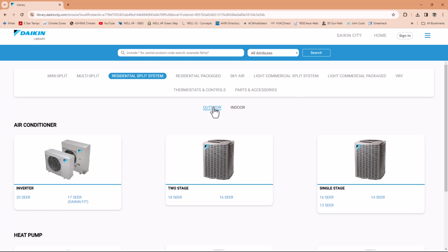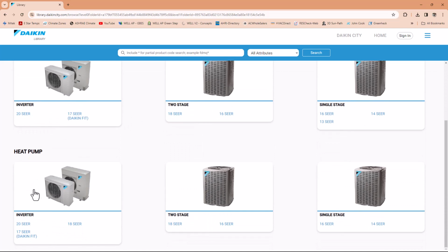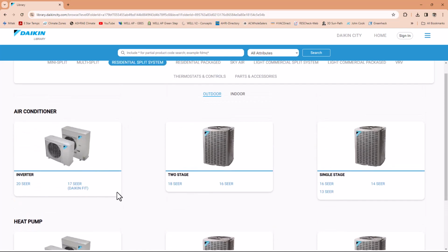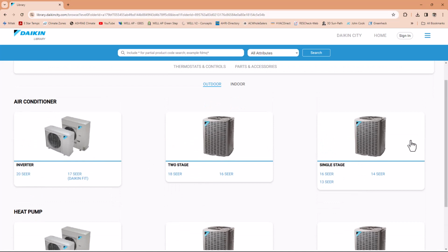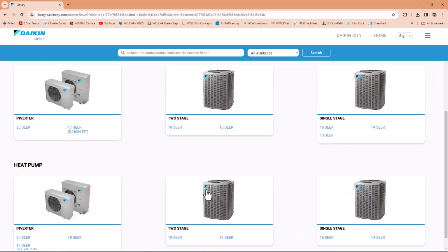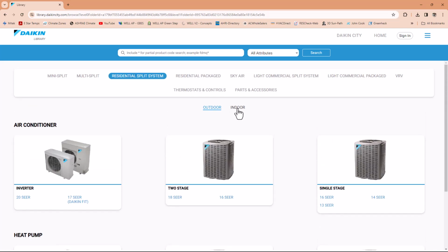And remember, this happened with me in commercial and in residential. Usually they call the indoor unit a heat pump too, and that's very confusing, because the outdoor unit in here says heat pump. These are all heat pumps, as you can see. The heat pump is the outdoor unit. Air conditioners are the outdoor unit if it's cooling only, but if it's heating, it's a heat pump. The indoor unit is not a heat pump. I mean, there's debate that yes, it's a heat pump because it also provides heating inside. It's changed because of the reversing valve, everything.